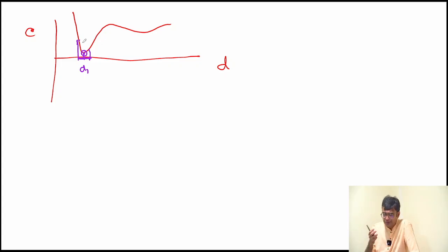So in RDO, the RDO will try to find a point, let's say this point. It's also one of the local optima, right? You change by the same amount. By drawing it is not the same, but you know what I'm trying to say. What is the change in your objective function? Almost zero, but not zero, very little. This point is an insensitive design point, right? This is a robust